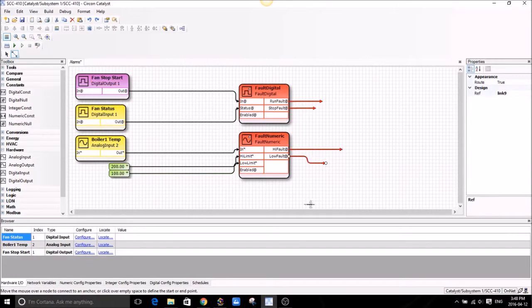So you can take those outputs and do some funky logic with it and have it do what you want. Have it turn on more relays or pass it on to the network to a LAN system, or pass it on to a Modbus system. Let's say you had a Modbus touchscreen and you wanted to trigger a light bulb or something on the Modbus touchscreen. So what you can do is connect this to the Modbus touchscreen and turn the light on or off.